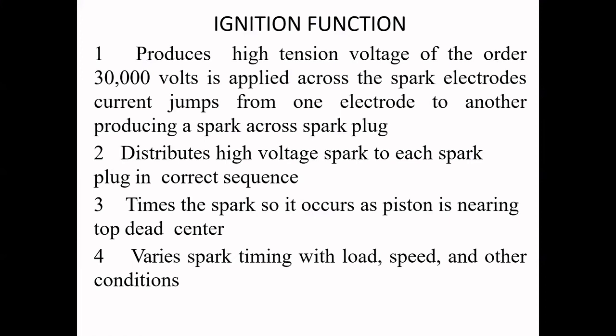Another point has to be taken care of here: timing the spark is very important in the ignition system. Theoretically speaking, the spark has to be produced when the piston reaches top dead center position, but this is not the case in actual practice. In actual practice, engines are designed so that the spark is produced before the piston reaches the top dead center position.